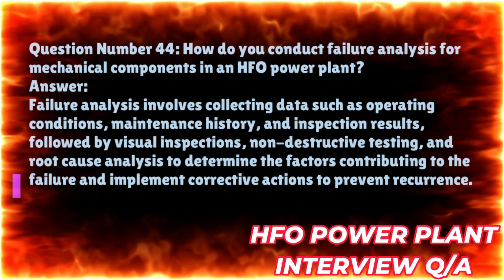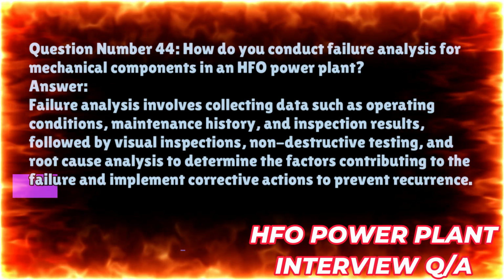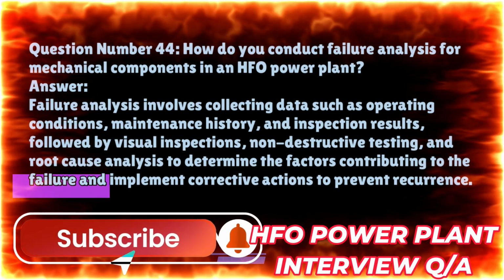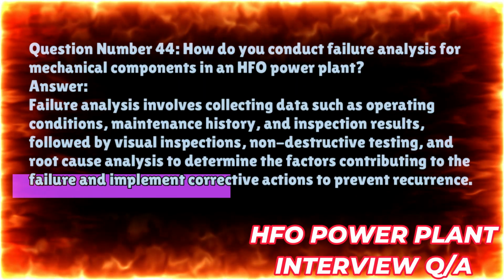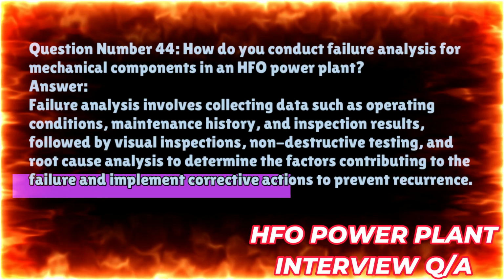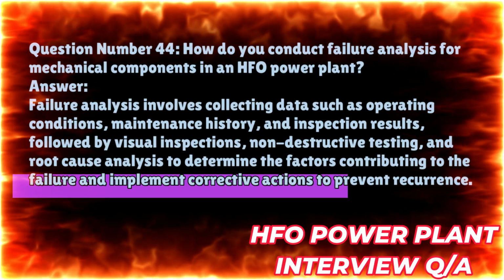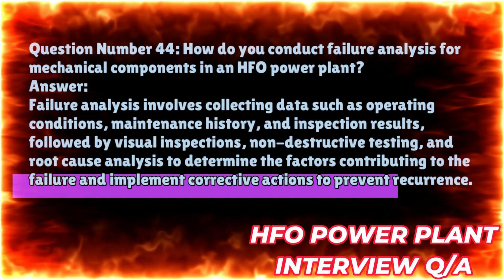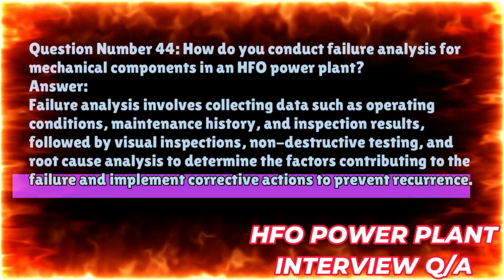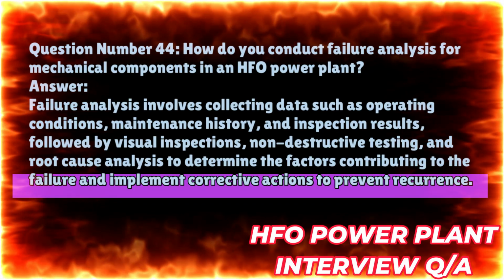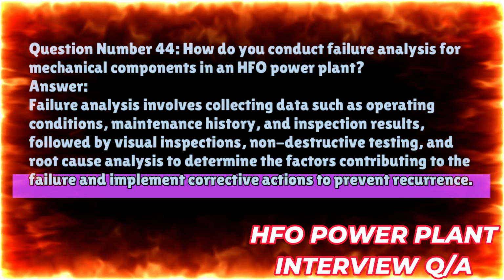Question number 44. How do you conduct failure analysis for mechanical components in an HFO power plant? Answer. Failure analysis involves collecting data such as operating conditions, maintenance history, and inspection results, followed by visual inspections, non-destructive testing, and root cause analysis to determine the factors contributing to the failure and implement corrective actions to prevent recurrence.